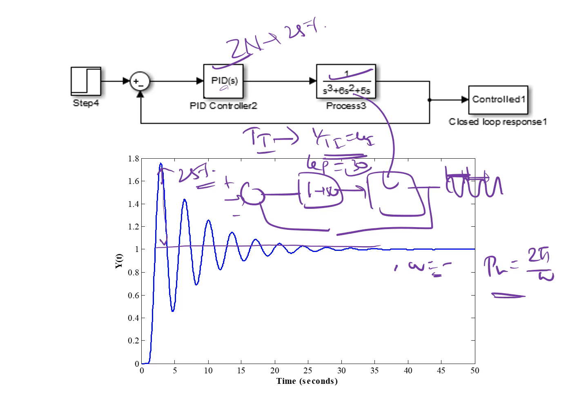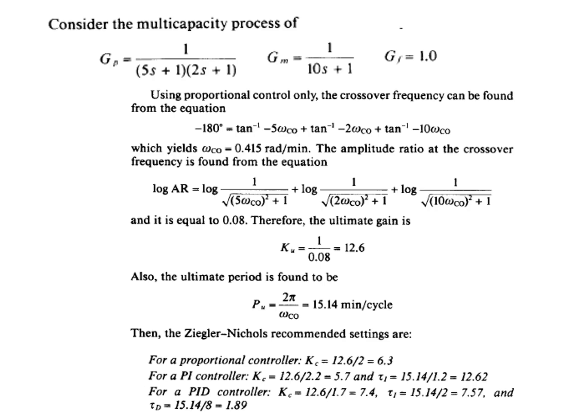Okay. So now we'll do this process using the Bode plot method. Okay. Yes. So this is the function. So here we can write the equation. Okay, so we know that. How do we write the equation? Because whenever we want to find the gain margin, we have to equate the phase to minus 180 degrees.